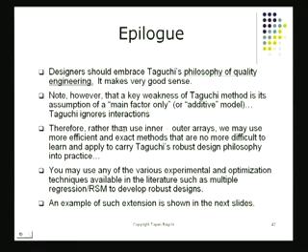One, of course, is that being at the target is the best. That's number one. Number two, you got to make the product robust. This is number two. It's very, very important. Number three, to conduct experiments, you should use orthogonal arrays. Many times these turn out to be quite all right. You don't really need fancy interactions to be incorporated in your analysis. Then, of course, the fourth contribution that he made, which is where some of the controversy is, is his recommendation that you should be using signal to noise ratios.